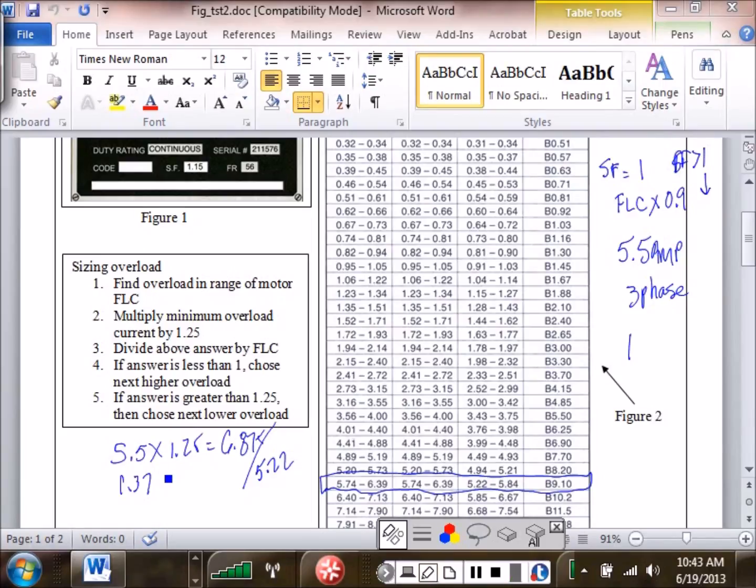You probably know what you're saying, but you're saying it wrong. In your mind, you know what you're saying, but when you say we'll choose the lowest, if you say we choose the next lower, then that would be exactly right. Because using this overload, we're going to overload it by at least 137%. And that's why we use the minimum. We don't use the maximum. The minimum is guaranteed. Y'all understand?